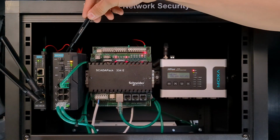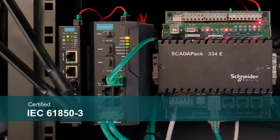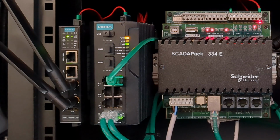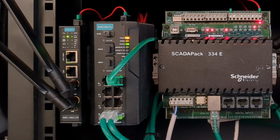This is an example of industrial-grade firewall from Moxa. Model name is EDR-G9010. Not only it has a rugged design with compliance to IEC 61850-3, but also provides several industry-specific software features, such as deep packet inspection and built-in intrusion protection system. Such a firewall could be used to secure wide area network connectivity from substation or remote site to control center, or to segment network of a large industrial site.